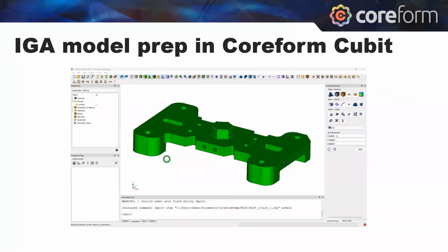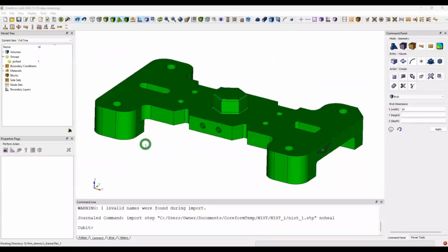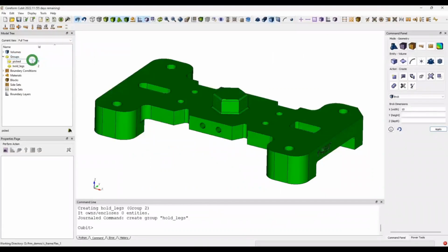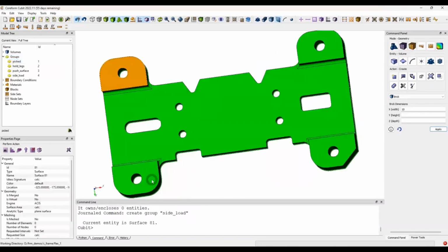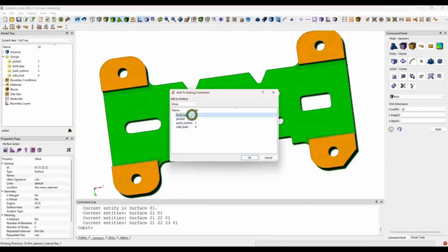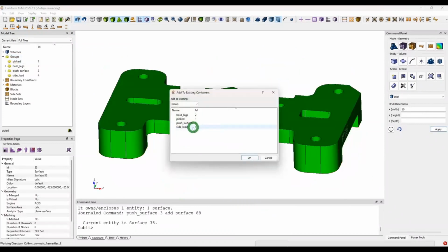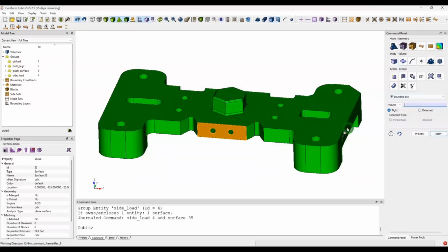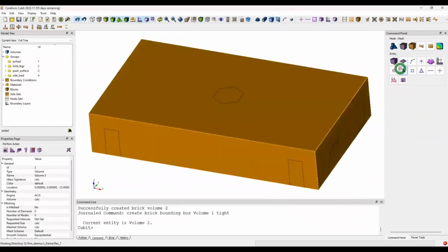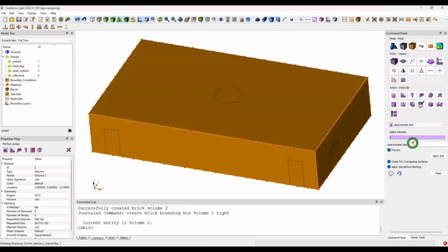And so now, taking the same model but using our flex representation method, which I'll introduce shortly, all we need to worry about is being able to build an envelope domain. This is only sped up, I think, like 50%. We're just going to, again, assign regions of our model to apply boundary conditions onto. So I'm going to say I want to apply a boundary condition onto these legs, and onto this top nub. And notice how I've not done any defeaturing of my surfaces, which I did in the previous model. And then I can build my envelope domain where the computations are going to occur.